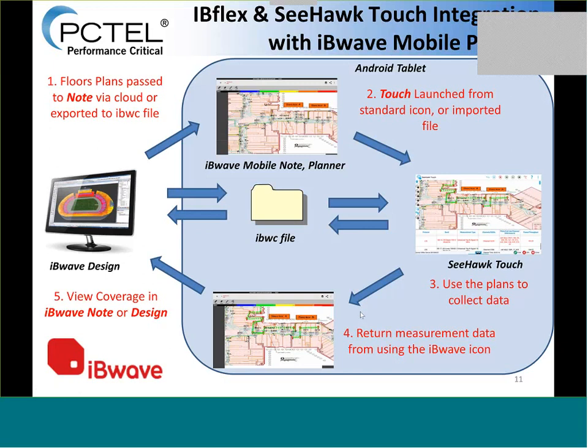IBWave has a way to handle these sets of measurements done at various points in the life cycle, so you can do comparisons: what was my baseline at the beginning versus the end? What was my predicted value versus my measured value? So in truth, you may go through this circle of bringing the fresh information back and forth 3 or 4 times during the life cycle.